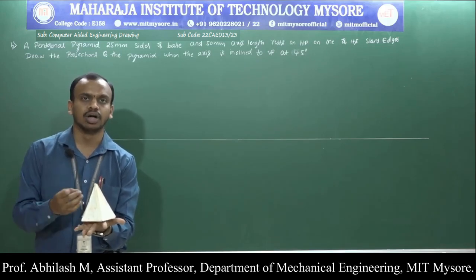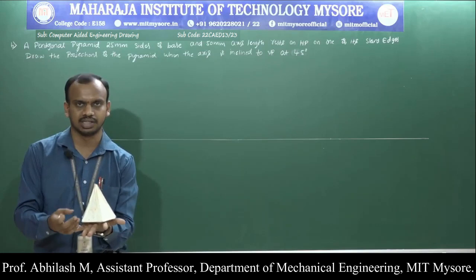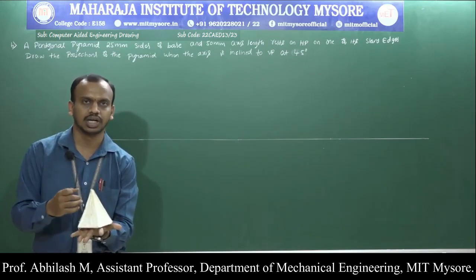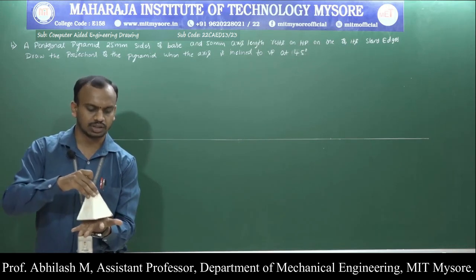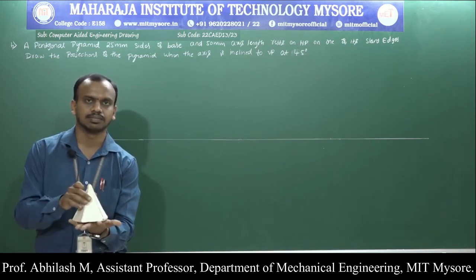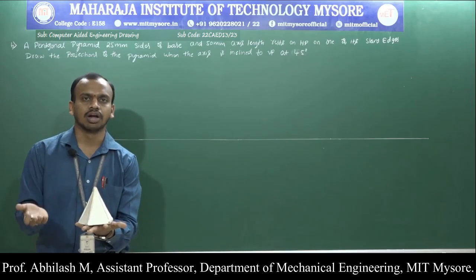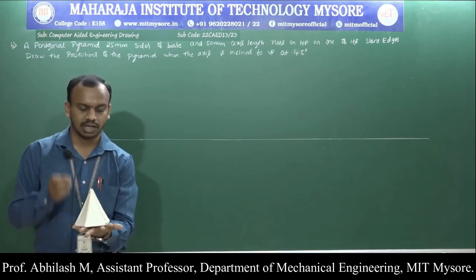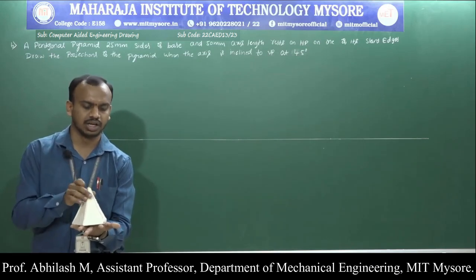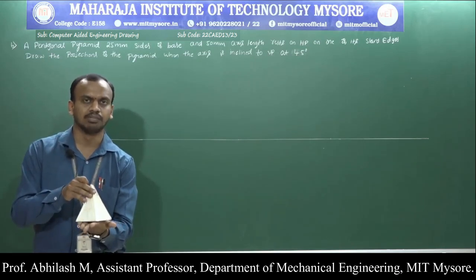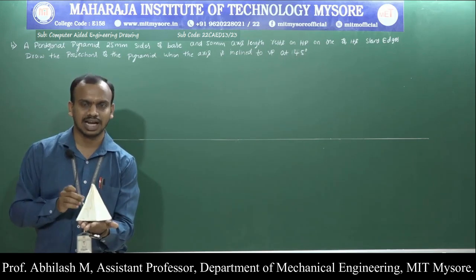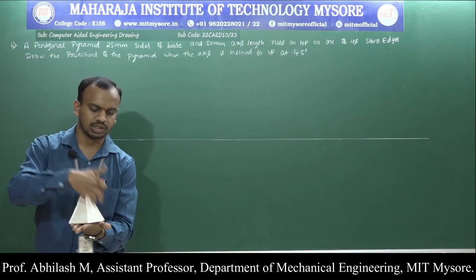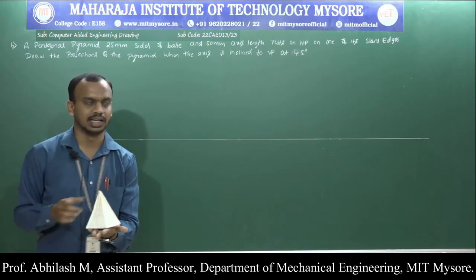If they had mentioned one of the triangular faces rather than the slant edge, if they asked to rest on the triangular faces, you would be supposed to rest it like this. Basically a corner or edge condition, as in the previous cases that you used to solve. Here they are specifically mentioning that we are supposed to rest the pentagonal pyramid on one of the slant edges, a corner condition of a pentagon. So this is resting on the slant edge.